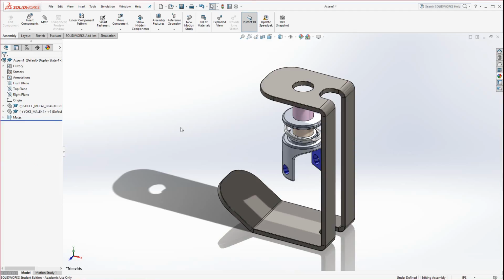Physical dynamics is a little bit more advanced. It's great for example, let's say you have a pool table and you have balls on the pool table. You could click on one of the balls and push it or move it, and the balls in its way will move out of the way. Actually, it will push them. But be aware it does not have moments of inertia or things like that, or gravity. Those factors are not included. It just simply pushes items out of the way.